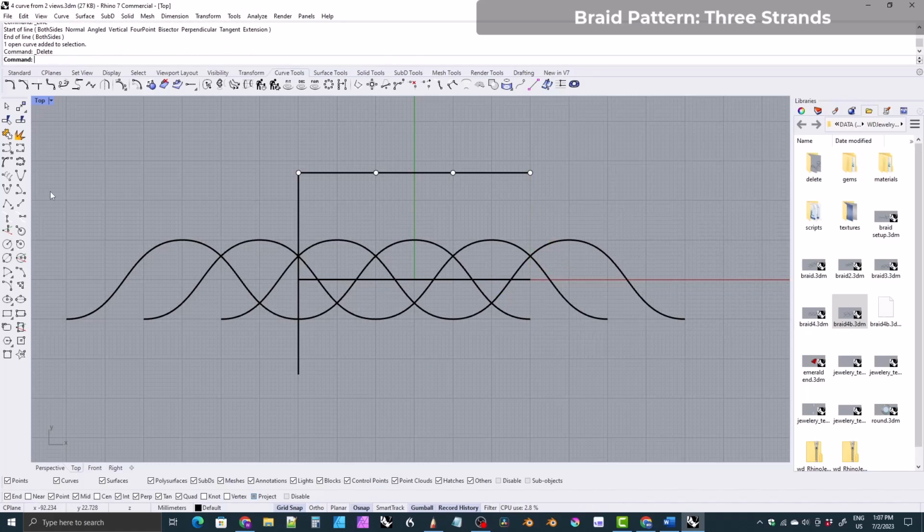I'm going to do that over again. You don't have to, but click here. If you hold Shift, that locks you into 45-degree angles, and that's why that helps you make a perfectly straight line. Okay, so come here and click. Well, it's always perfectly straight. A line is always perfectly straight in Rhino, but it helps you make it perfectly vertical, is what I mean to say.